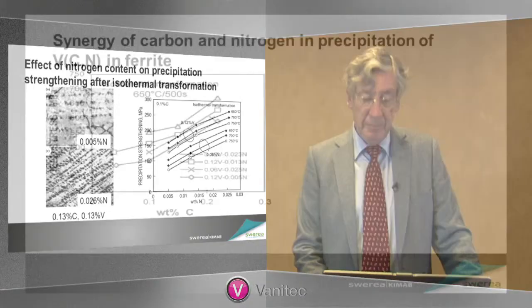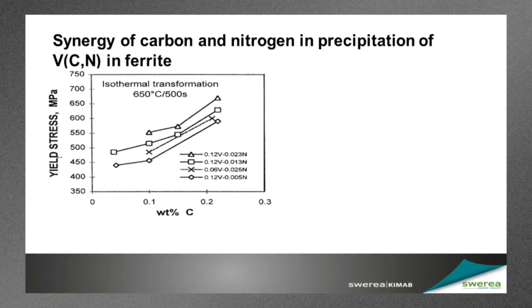This is, in this case, principally a result of the refinement of the vanadium nitride particles, which are improving the hardness and strength. Now I'd like to turn to an interesting synergy. We've talked about nitrogen, and now I'm going to raise an additional effect of carbon levels. Now, you might well say, well, everybody knows that carbon increases the strength of steels.